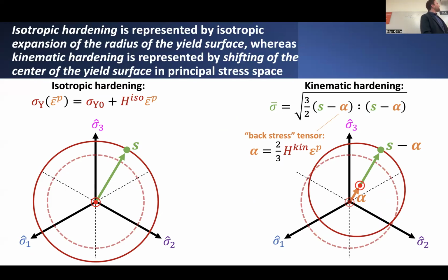And one way to include that dependence is supposing that the yield stress itself depends not on the total plastic strain, but on the equivalent plastic strain, that kind of variable that is always increasing and is basically just a single scalar number. And if we suppose that the yield stress depends strictly on the equivalent plastic strain, then our yield surface, originally some kind of cylinder in principal stress space, will look like it's getting bigger with increases in equivalent plastic strain.